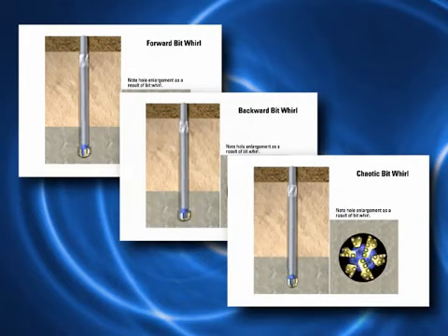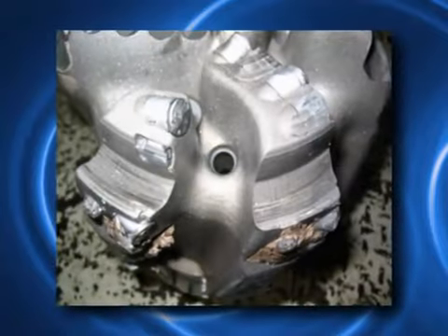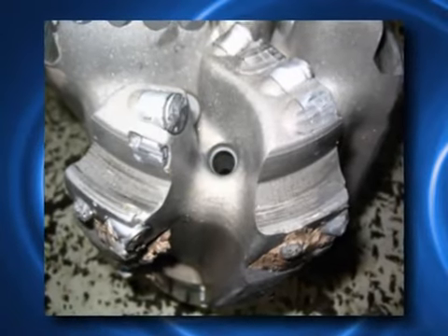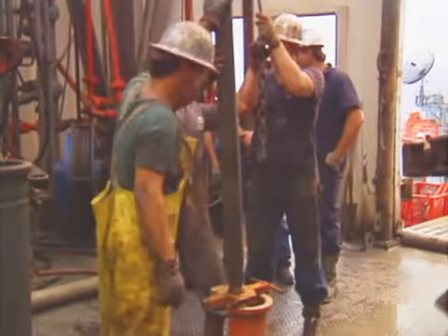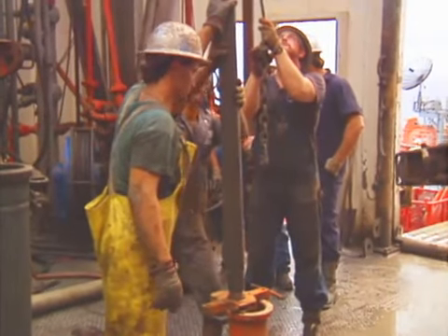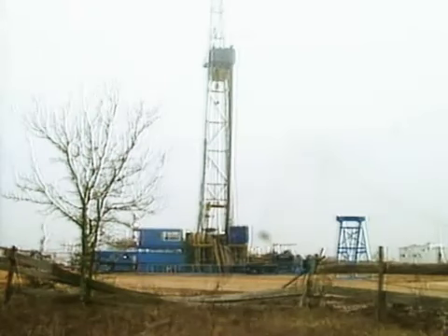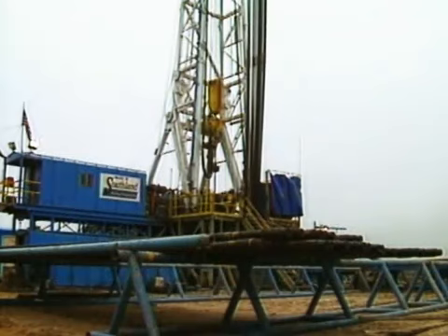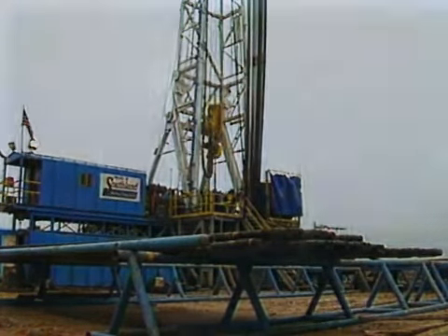Verification of shock and vibration can often be obtained by examining the bit after a trip. When dealing with BHA whirl, it is sometimes necessary to stop drilling completely to cure it, depending on the severity of the shocks and difficulties with drilling.